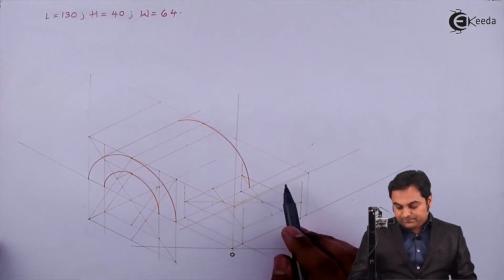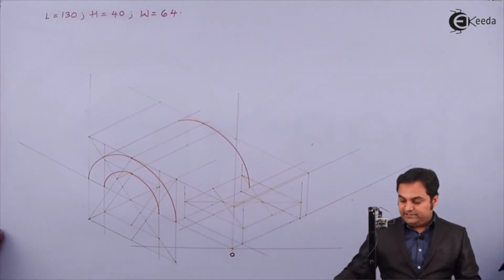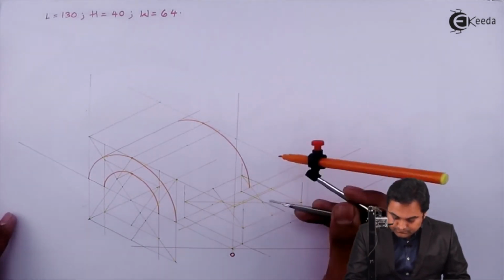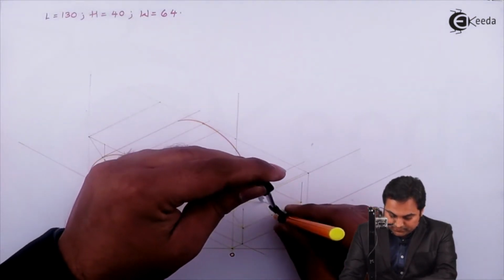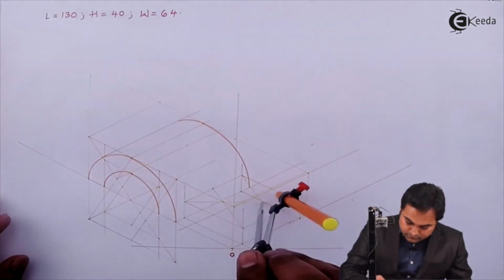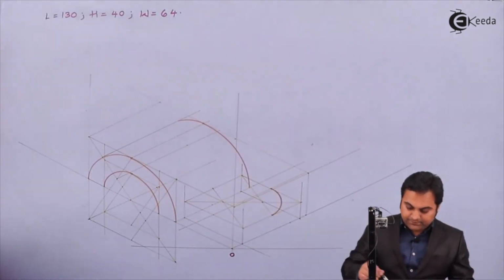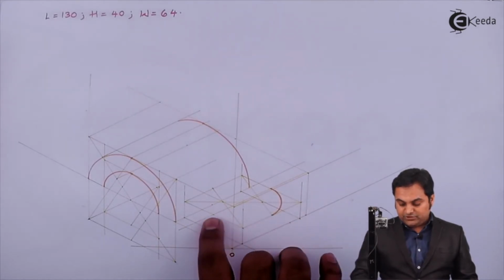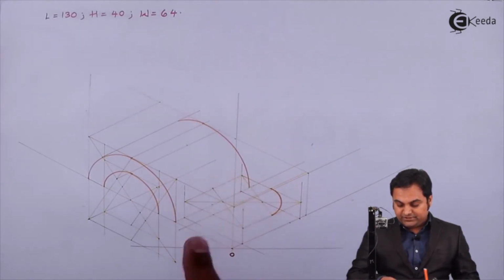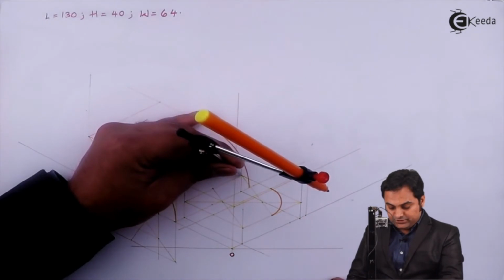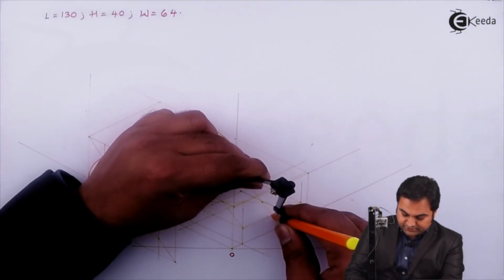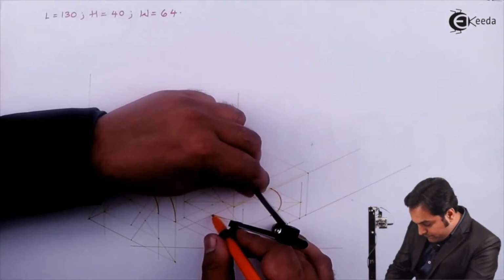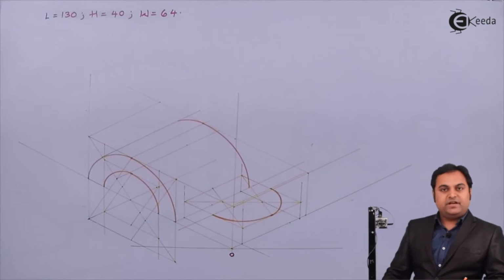So this is the line at which the semicircle should end, and the procedure is, first I am taking this center and taking radius up to this end, joining them. Next I need to connect this arc up to this midpoint. For that I am choosing this center, which is at this location, measuring this radius. So this is the semicircle which I am getting.